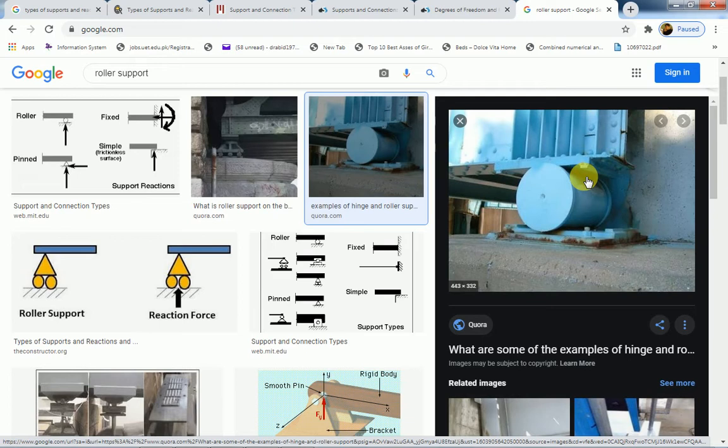So thermal expansion of materials is always there with the change of weather. To allow the materials to expand in summer and to contract in winter, you have to put a roller-like support. Otherwise, if we fix the supports of steel bridge edges, it will surely break the fixed supports.